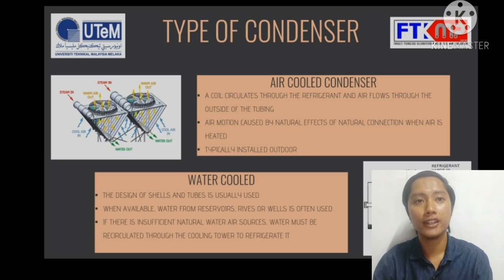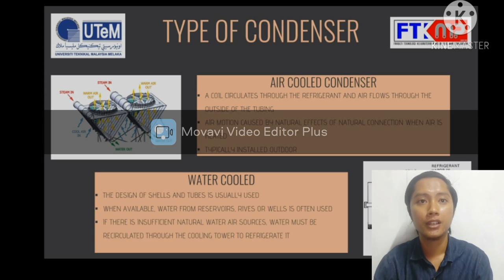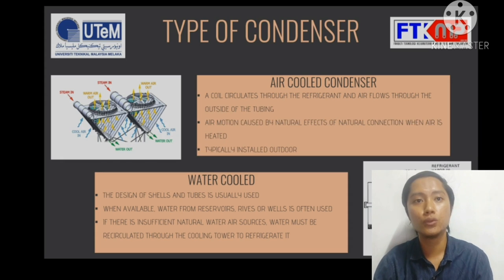For air-cooled condenser advantages, it is used in locations where water is difficult to use. It has very simple construction. It has low initial cost and maintenance cost. It has less piping work to do. It has less chance of fouling. And it is very easy to clean.